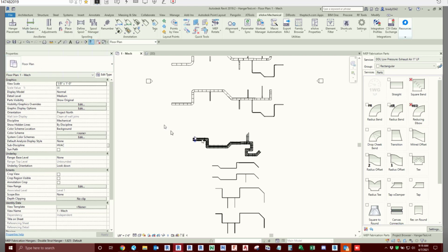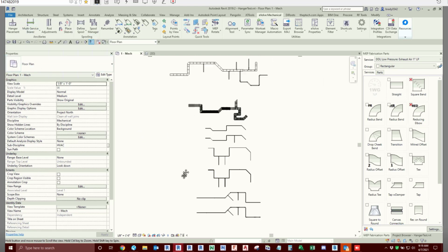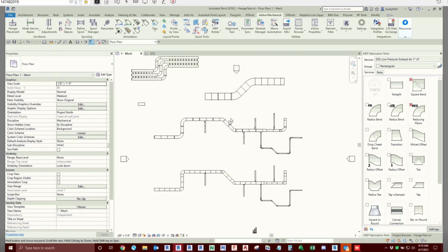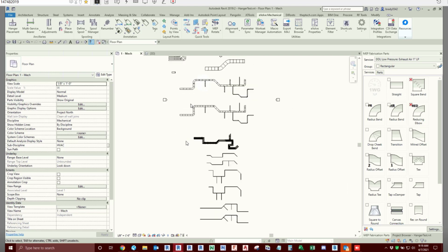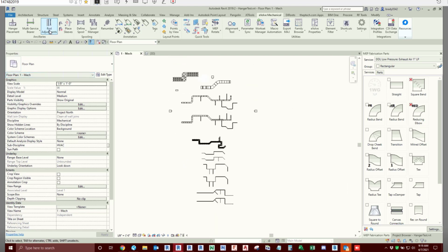No? Okay, now we're going to get into rod adjustments. And again, that's why I wanted to do rods on some of the ductwork, and this will work well too. What this is actually for is placing inserts in the deck, or extending rods up into the deck. If you want to add a little bit of extra rod on the end of your run on the top of it, things like that.